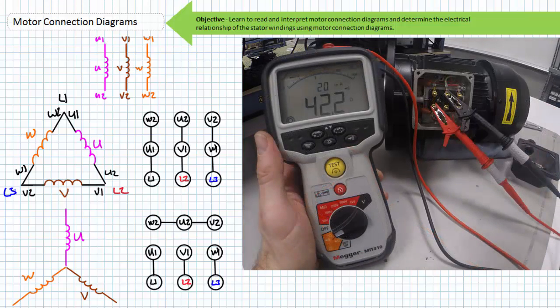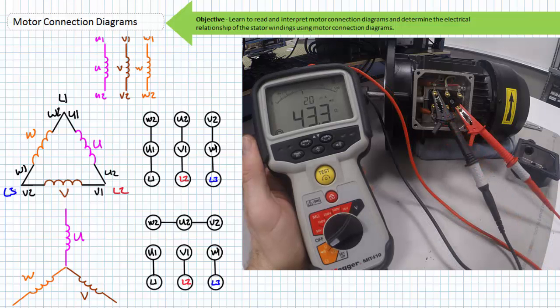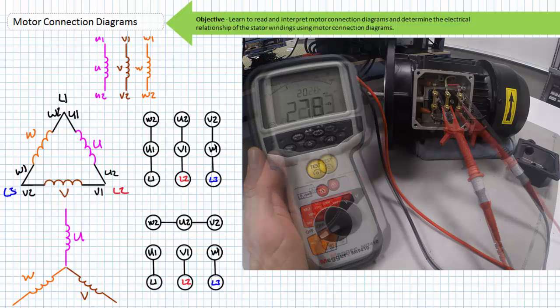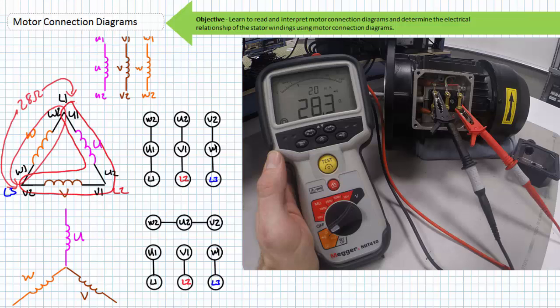When we remove all the jumpers and check the resistance of all 3 coils, the ohm meter says that they're all around 42-ish ohms. When we reinstall the jumpers in a delta configuration, note that an ohm meter used to check resistance from either corner sees around 28-ish ohms, which is the series combination of 2 windings of the opposite corner taken in parallel with the corners being inspected.